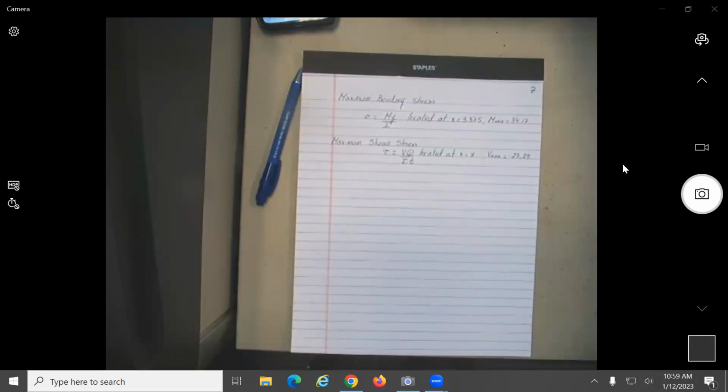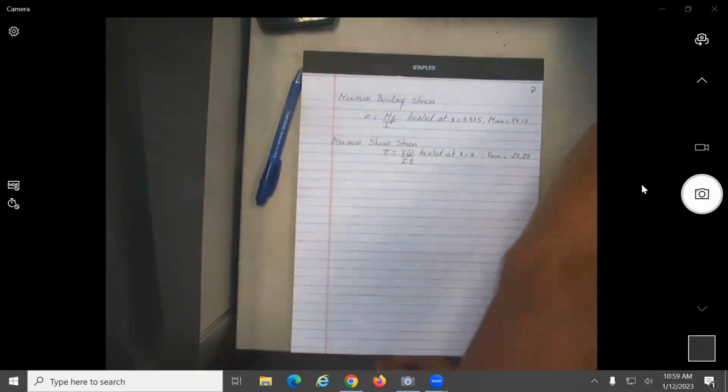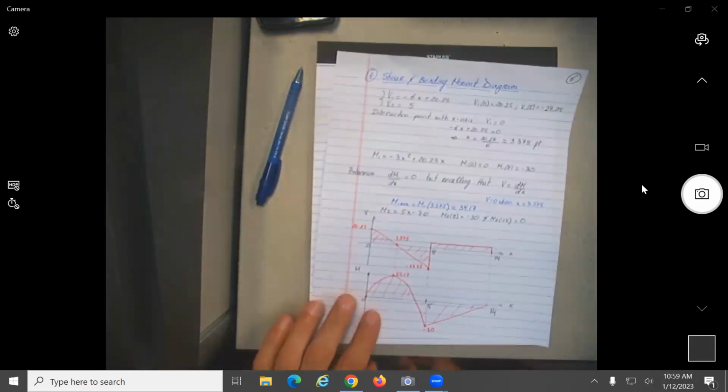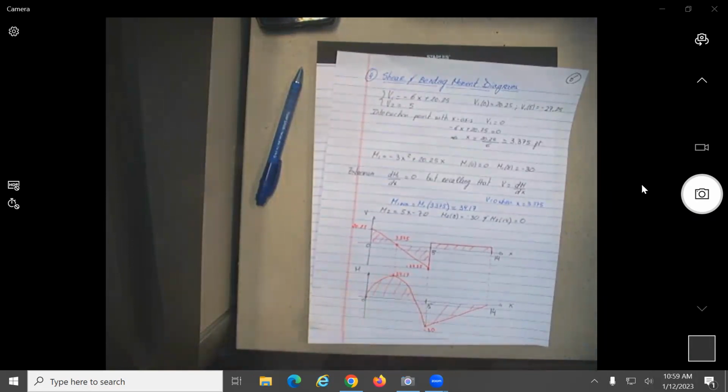Last thing, we have 1 minute. Here's an example, but can the bending moment diagram be discontinuous? By meaning discontinuous, can it have a jump over here or anywhere? It cannot, because maybe you study that, you don't always study this stuff.